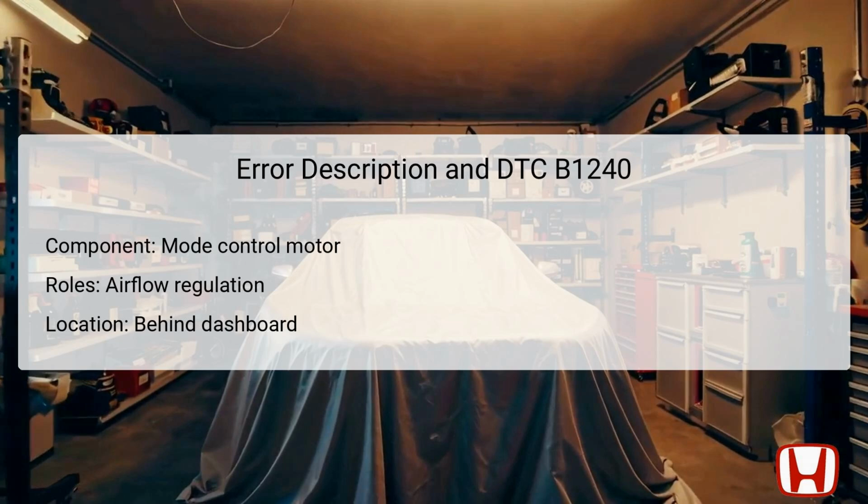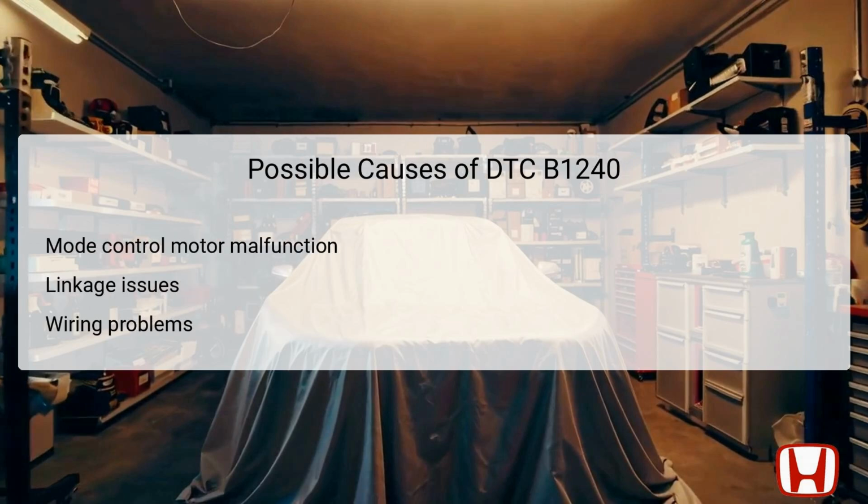Identifying the fault requires detailed troubleshooting steps to confirm whether the issue is rooted in the motor, its linkage, or electrical connections. The potential causes for DTC B1240 include several key areas of failure. Firstly, a malfunction in the mode control motor itself could prevent it from effectively adjusting airflow settings. Secondly, mechanical issues with the linkage that connects the motor to the air distribution doors may cause restrictions or failures in operation.